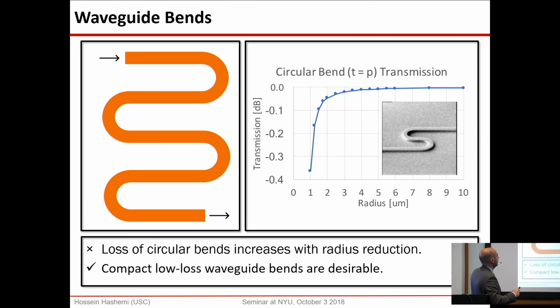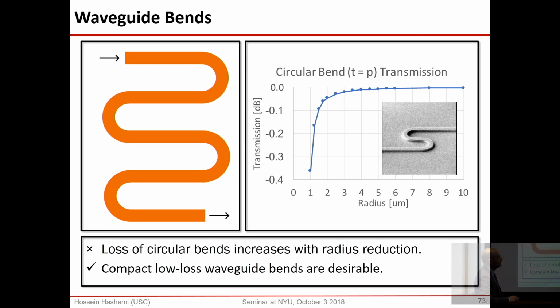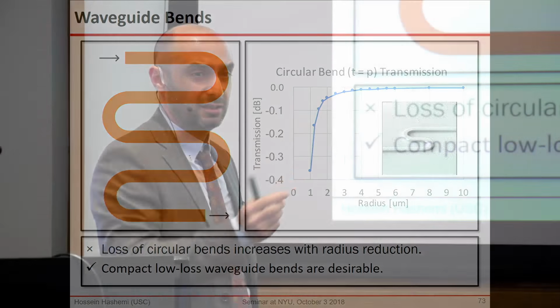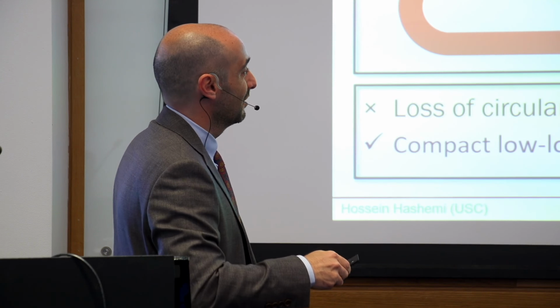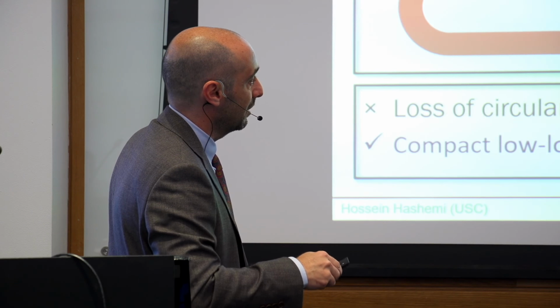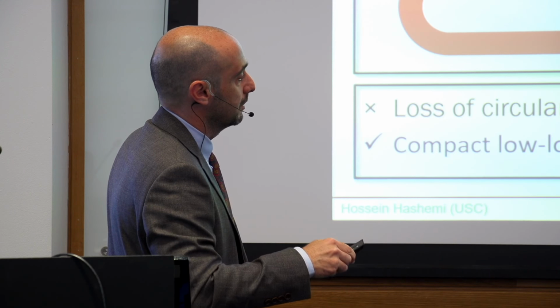Now, once you have a waveguide, you can even bend the light. So this is a waveguide that just bends like this. And the bends can be pretty tight. This is a SEM of a structure we taped out, so you can see the light can be bent. And depending on the curvature, the loss is going to be more or less. If you bend it really tight, the light cannot really bend that fast, so the loss increases. And if not, the loss is pretty okay.